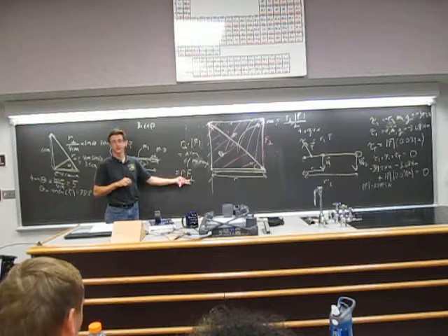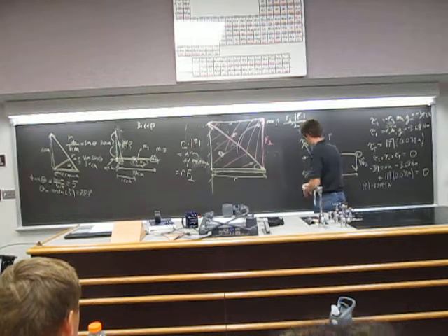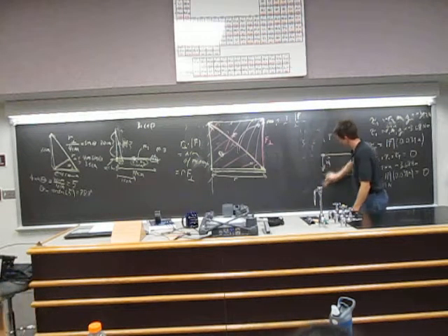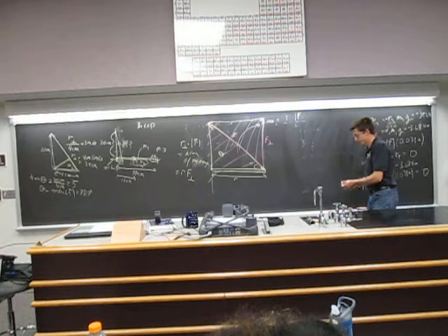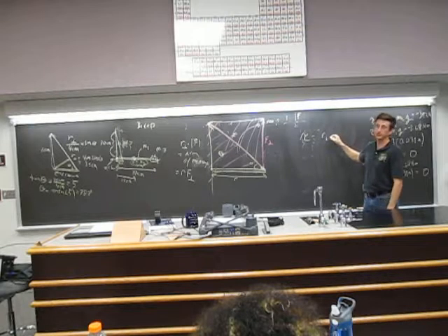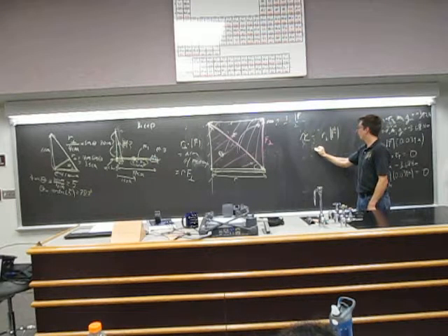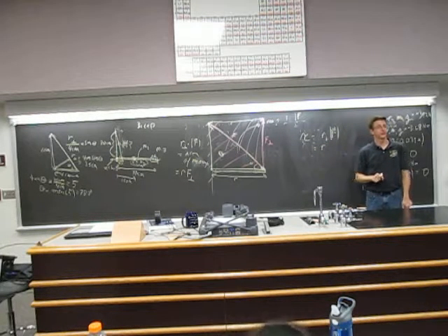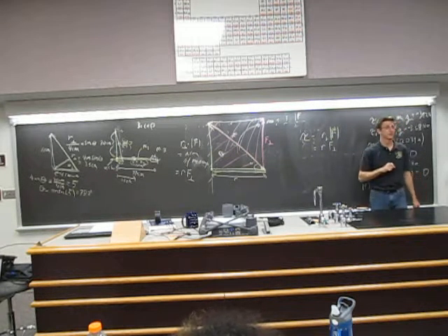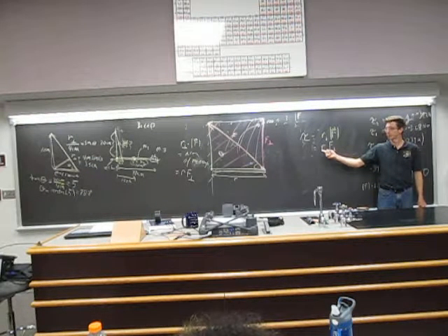So this is another way to write the torque due to a force. The torque can also be written as either the perpendicular distance from the pivot point to the force times the magnitude of the force, or the distance from the force to the pivot point times the component of the force that is perpendicular to that distance.